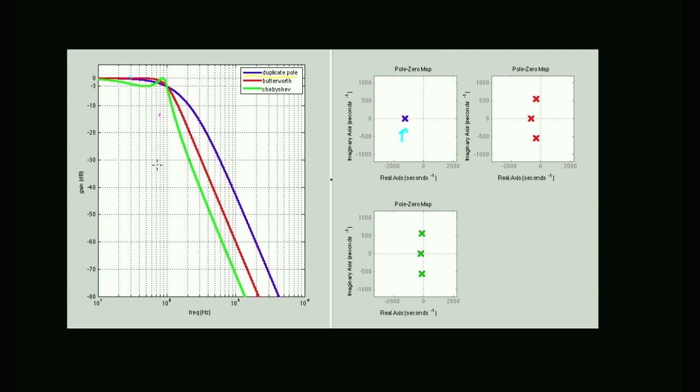I don't want to get too much into detail on this. What I do want to get into detail on is, suppose we decided to build this filter. For whatever reason, you played around with this, you decided you needed a Butterworth filter, and a third order filter was good enough. So this is what you want. How do we build it? How do we actually make that circuit? This gets tricky, because we know the math, but we don't really have a good circuit to make this. My goal between today and Friday is how to build this circuit. The first thing I need is to know where those poles are, where these X's are.